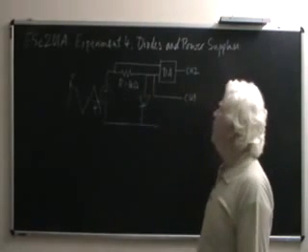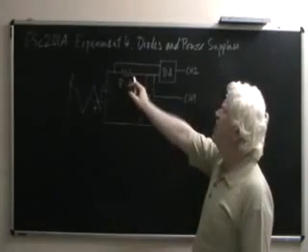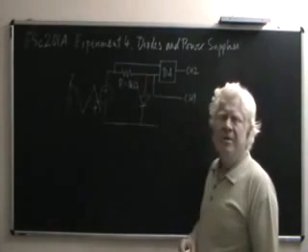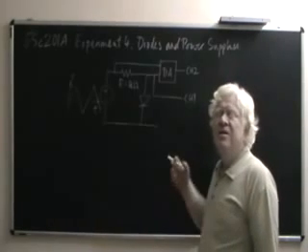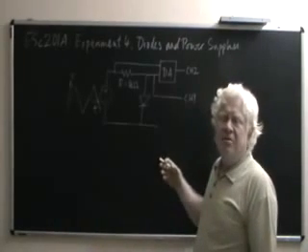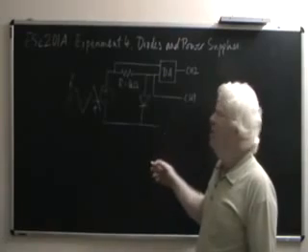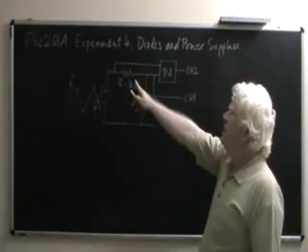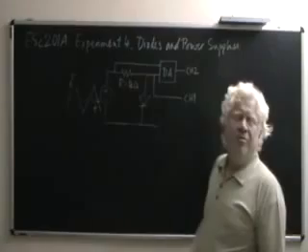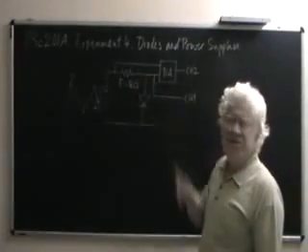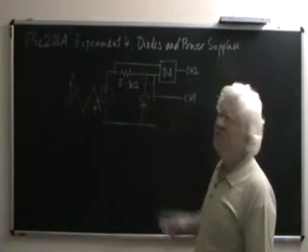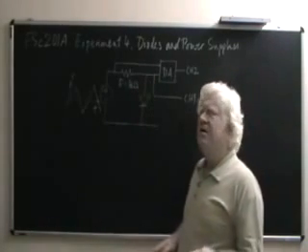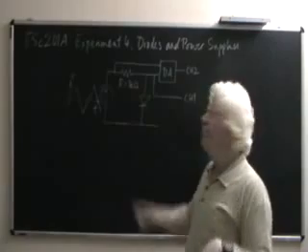Now clearly what we want to do is to measure the voltage across this resistor and recognize that being a linear resistor, the voltage is indicative, though not numerically equal, to the current of the diode and the resistor, which are in series.